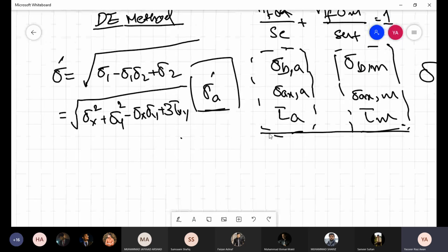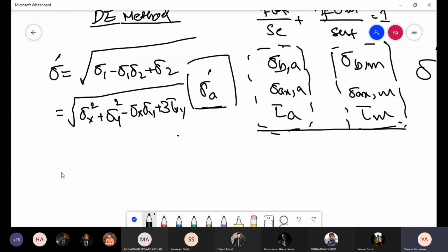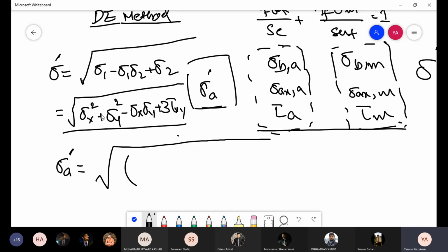So when we are faced with this combination, what we do is find the alternating von Mises stress. Generally, in shaft cases you have an axial load on top of bending. We basically use this equation, but generally on a shaft under bending, you have only sigma x. So bending stresses and axial stresses usually are in the same direction, so they superimpose onto each other.